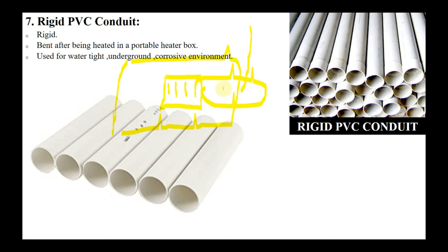So now you have two options, but you will have to run the conduit underground. So the problem is that there are some sort of conditions when you are running your conduit underground and PVC fulfills all these conditions. So that's why we will go with PVC here. So in this specific area when you have to run the conduit towards the wall, you will use PVC here because this conduit will run underground, and then we will use EMT here.